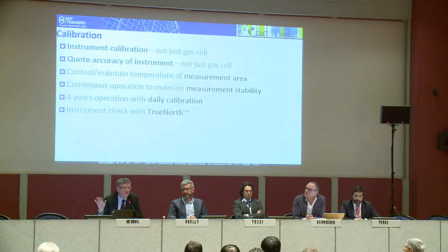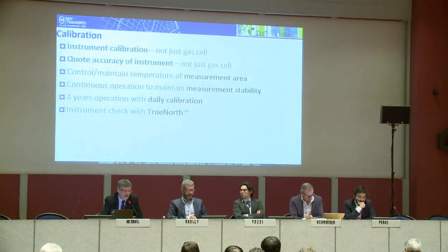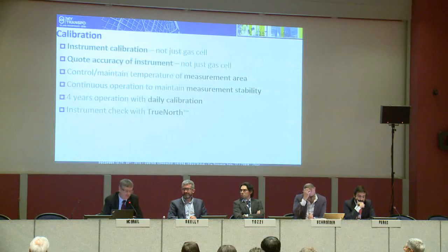They will go through the columns, we will detect them, we'll measure them. If we're going to go through a cell which is a headspace cell and using infrared, there'll be reflective paths, and any contaminants are going to be condensed on the mirrors. You'll get oil. We found this to our cost when we developed our own portable FTIR system. And you'll also get moisture. These will affect the way the system operates.